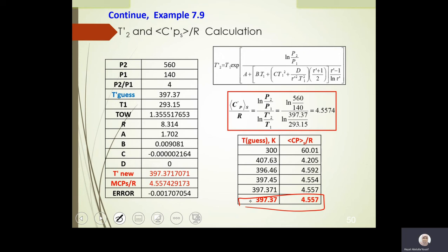This is the pumping system, and as we did with the compressor and turbine, the efficiency is given here. First of all, we need W, the work of the pump. They also need the temperature at the outlet and the entropy change, delta S. And for those three, I have equations. As I mentioned previously, the efficiency will be very useful because it will help me relate delta HS with delta H. And then the question here: how to get delta HS?